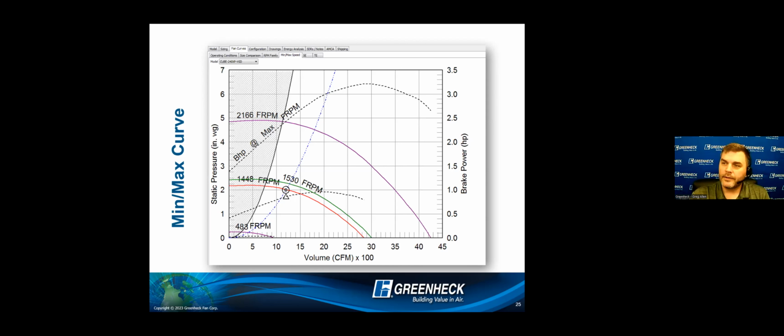That is gold to have for knowledge as you're picking and specifying air movers. Maybe you're in a situation where phase one, I need to move 600 CFM, but for phase two, I need to move 1200 or 1300. Am I procuring different fans for each phase, or can I order one fan that has the legs to overcome multiple phases of this project? Or maybe I have a situation where it's normal operation versus alarm or emergency operation.